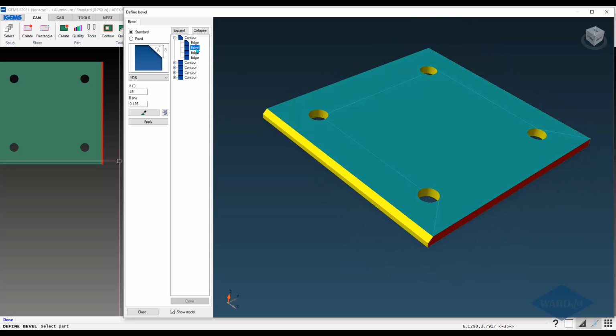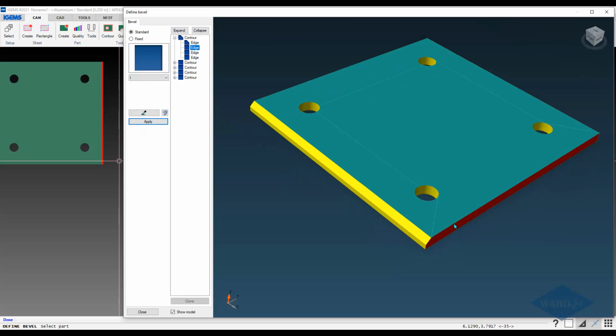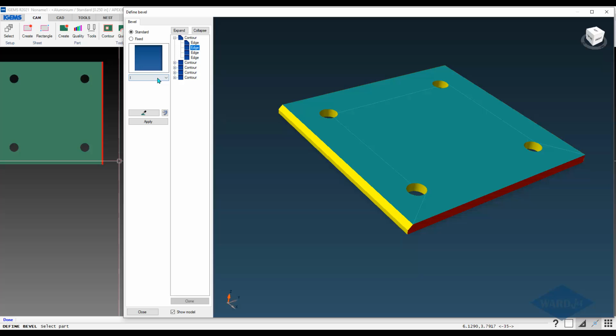And if we wanted to also put the same bevel cut on this edge here, you can just click on that, apply. If you decide you don't want to do that, you've got the undo button. There's also the choice of the eye, which is basically the same thing where it'll make the edge straight again. So we'll go ahead and put this back on there.